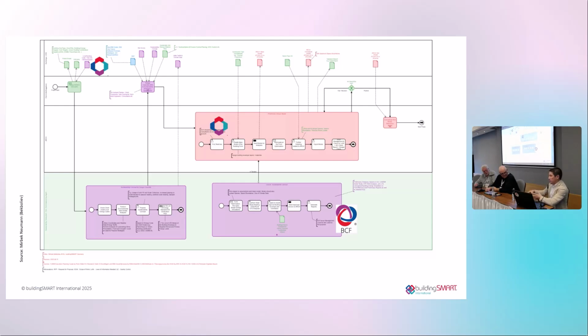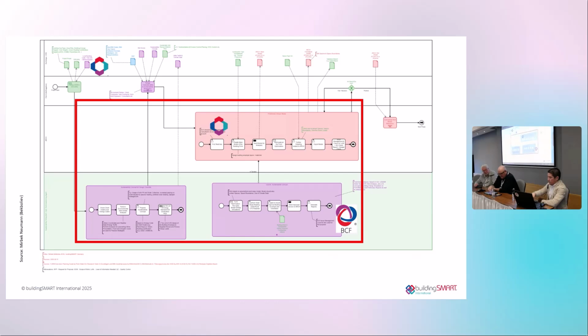There is no universal model that will be applied to everything, because some use cases are not interested in U values. In that case, for daylighting, I'm not interested in the U values of the window. I'm more interested in the G value, like what the transparency of the glass will be, or how many glazing layers there are. By the way, there is a property in IFC for windows and doors. Yeah, we went through that.